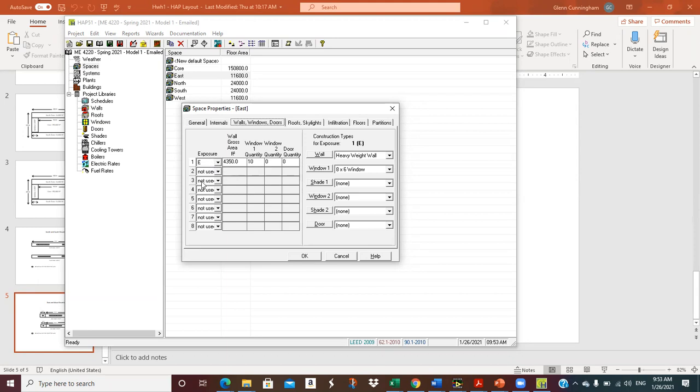Okay, so here you put the exterior exposures. So the only walls that go in are ones that are losing heat. And if it's losing heat to an unconditioned space, we have to put in a partition. That can happen, but that's usually pretty minor. Maybe you've got the boiler room under you or something, and so you have to do something a little bit for that, because you want to have that heat transfer in the model. But generally speaking, these are exterior exposed walls.